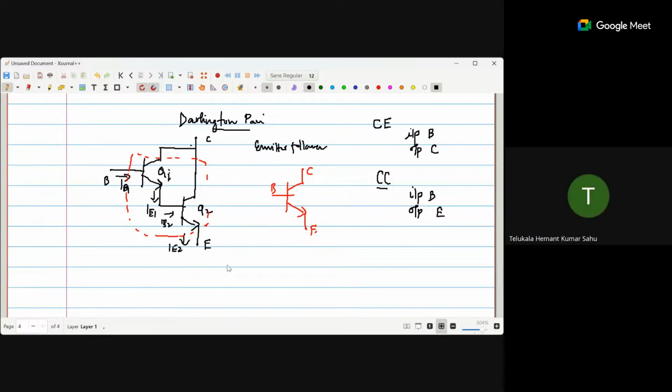Okay, so now here, Darlington pair is always called emitter follower, na, ma'am? Yes. Maybe we haven't seen it exactly in the amplifier configuration. We have only seen it with this beta multiplied. There you can see we will be taking the output from the emitter. So it is actually the emitter follower, common collector configuration.